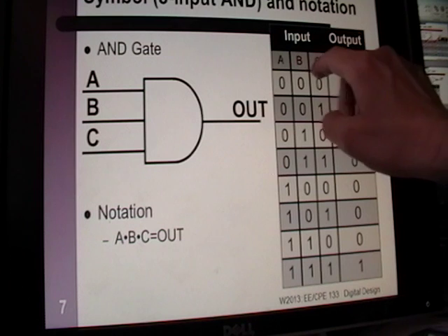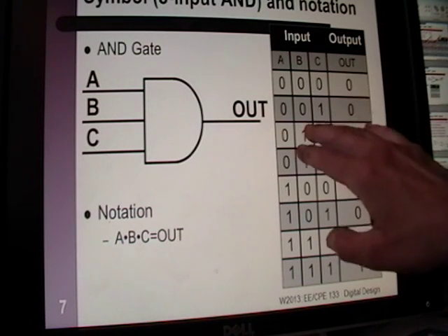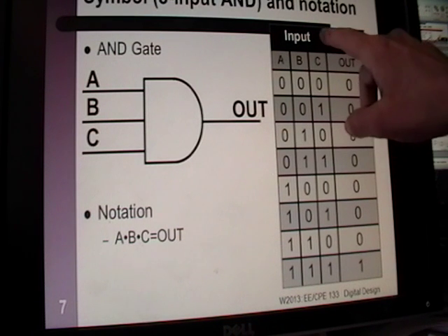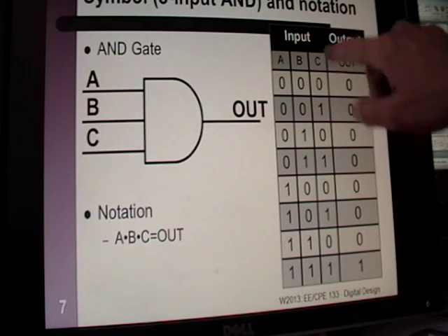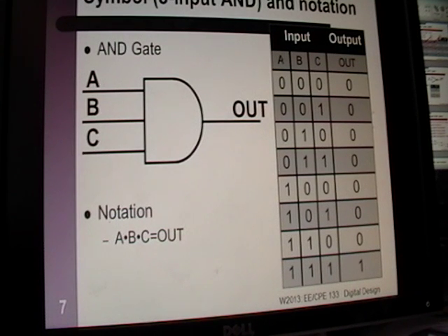When you increase your inputs, all combinations of inputs need to be included on the input side of your truth table. Maybe later on, when you get used to designing, you can skip a row or 2 or 5, but right now, just getting used to this, never ever ever skip a row in your truth table.